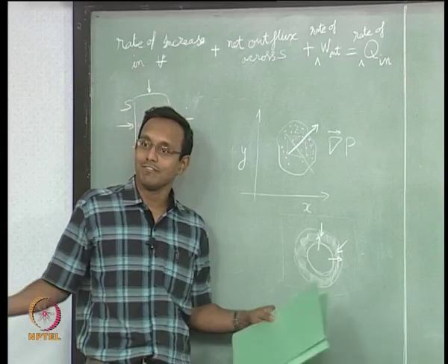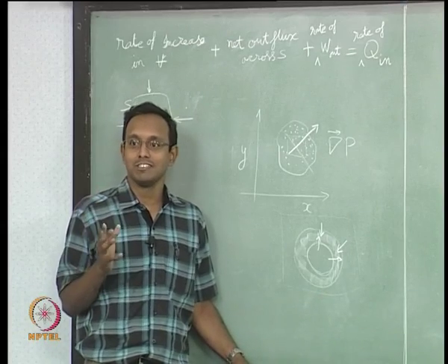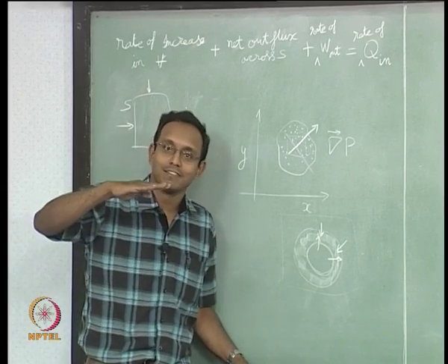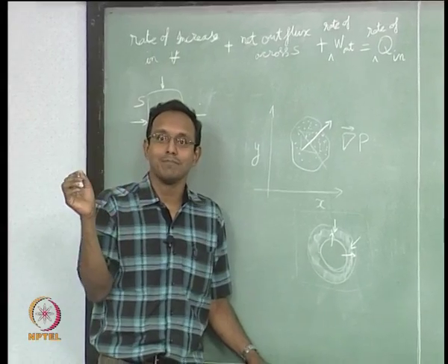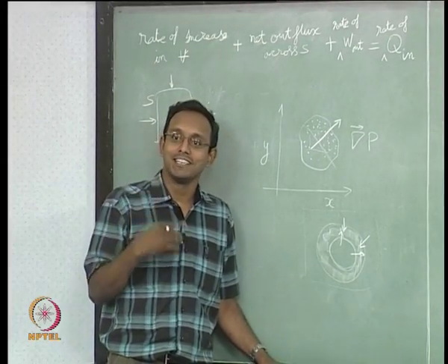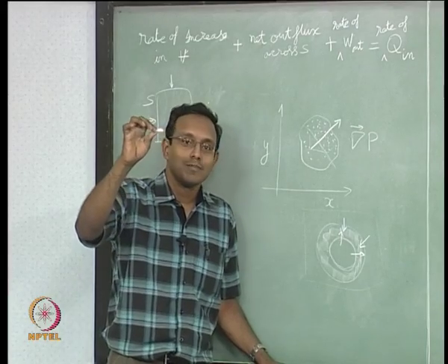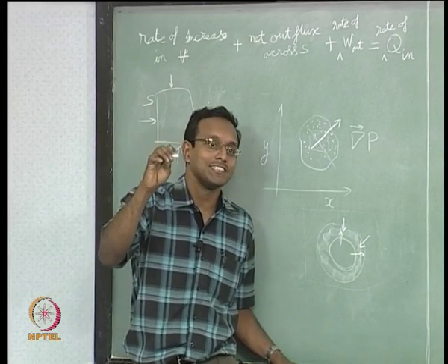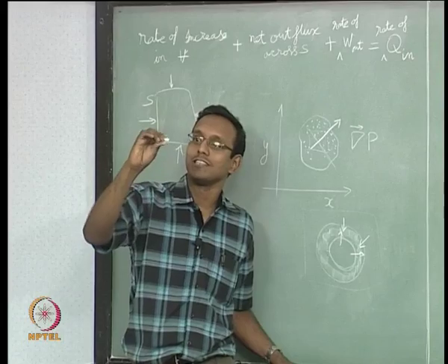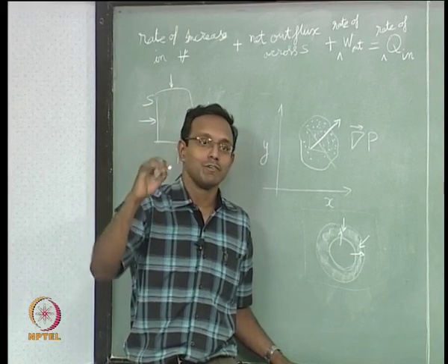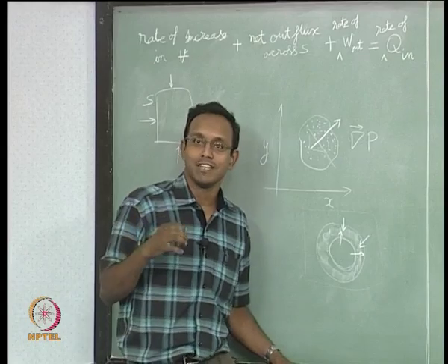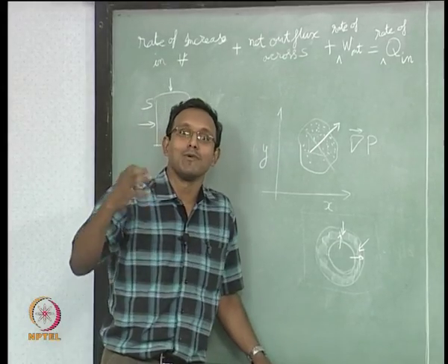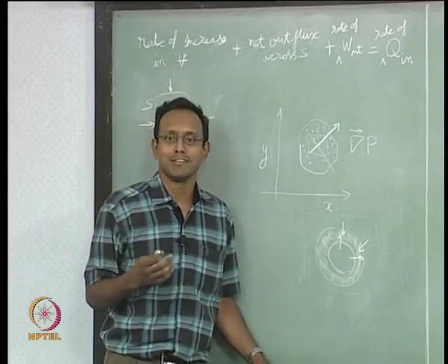If it is flow over an aircraft, then I am not bothered about lengths of less than 1 centimeter probably. Okay. If it is flow over my hand, then I may be interested in lengths of the order of 1 millimeter, but not anything lesser. If it is flow over this chalk, probably I am interested in less than 0.1 millimeter or so, because the overall size itself is somewhat small. The overall size itself is roughly 10 mm or something. So, we may be interested in something much more finer, that can also happen. Depending on the problem, you may want to resolve more, that is for people who want to go computational more, others it does not matter so much.